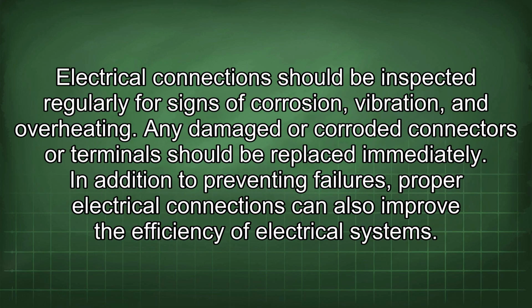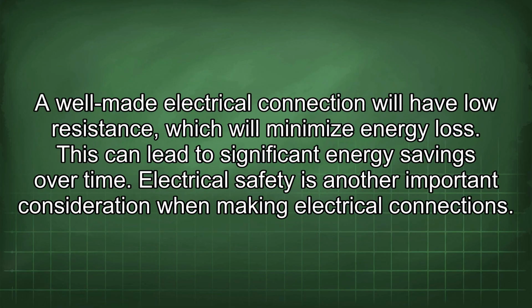Electrical connections should be inspected regularly for signs of corrosion, vibration, and overheating. Any damaged or corroded connectors or terminals should be replaced immediately. In addition to preventing failures, proper electrical connections can also improve the efficiency of electrical systems. A well-made electrical connection will have low resistance, which will minimize energy loss. This can lead to significant energy savings over time.